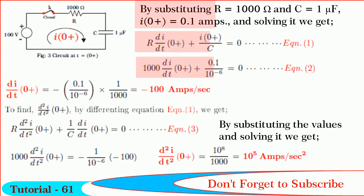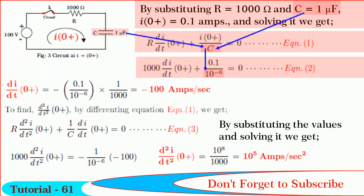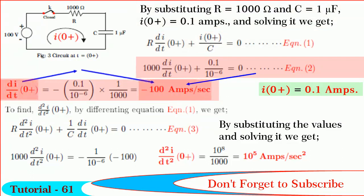Friends, by substituting R is equal to 1000 ohm and C is equal to 1 microfarad, I0 plus is equal to 0.1 amperes and solving, we get di by dt 0 plus is equal to minus 100 amperes per second.